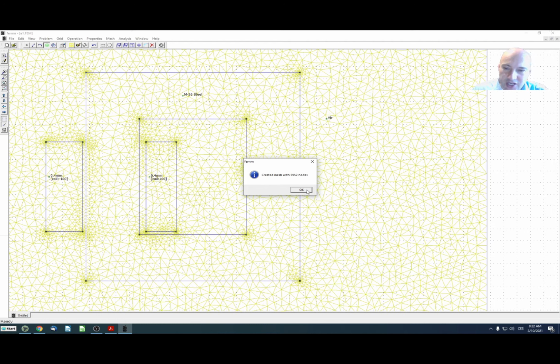You can of course adjust the precision of your calculation and the number of nodes in the mesh. Now how does the finite element method work? You see those triangles, and in every triangle we create a set of differential equations that describe the magnetic field. Right now we have about 6,000 nodes here. So in total we will need to solve a few thousand differential equations. But on a computer it's quite fast.